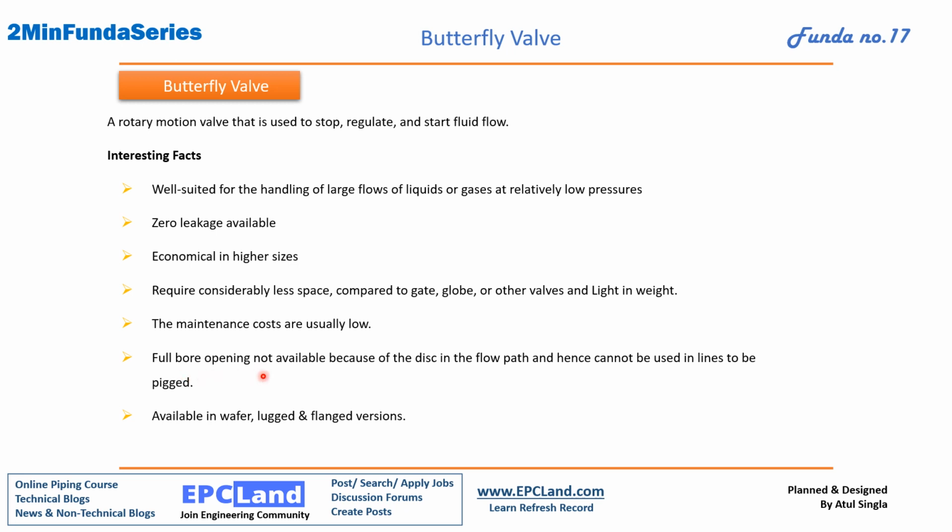Full bore opening is not available because of the disc in the flow path, and hence it cannot be used in lines to be pigged. Available in wafer, lugged and flanged versions. This we will discuss in detail in the next slide. Here what we have discussed, the disc is moving 90°, so it will obstruct the path, so full opening is never possible.